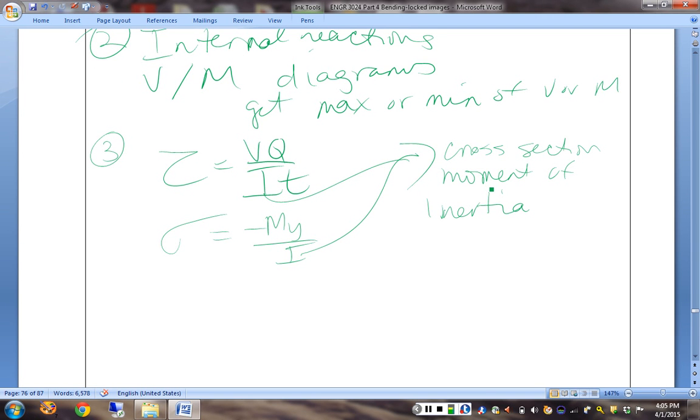Make sure that you pick out the I sub whatever, because this may be labeled X or Y, or it might be labeled Y and Z. Whichever way, make sure you pull the right one for the way that the beam is used in your loading scenario. So I sub whichever one is appropriate. So you get your moment of inertia.